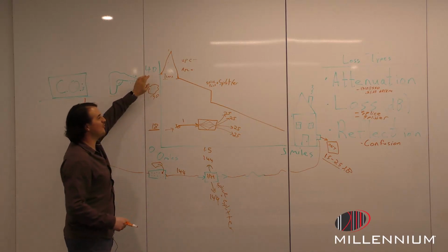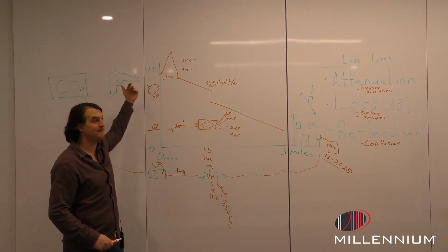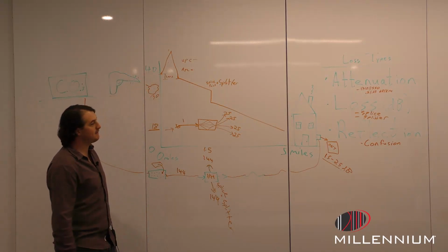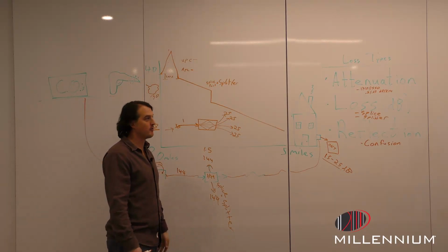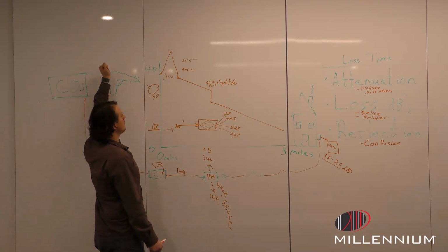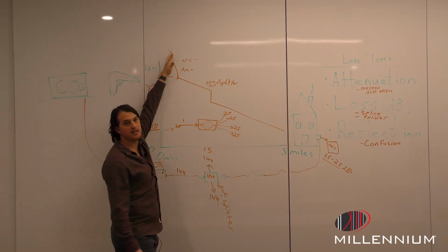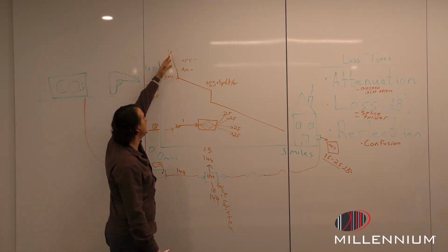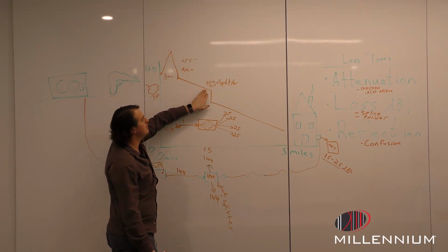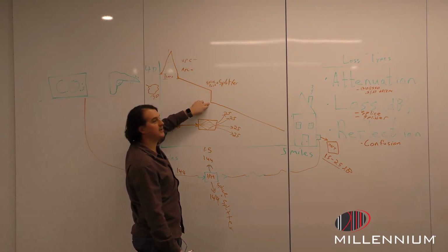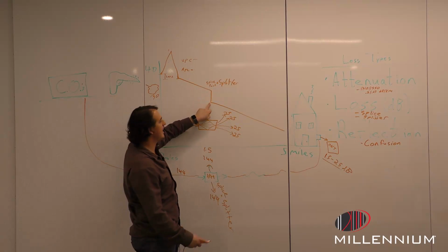And then the OTDR also shoots out 1550. And 1550, let's think of that as a long bed pickup truck. All right, so now that spitball, 1550, goes flying through here. It sees the connector the same way 1310 does, and it goes down our cable, goes through the splice point and splitter. Same effect, doesn't care.